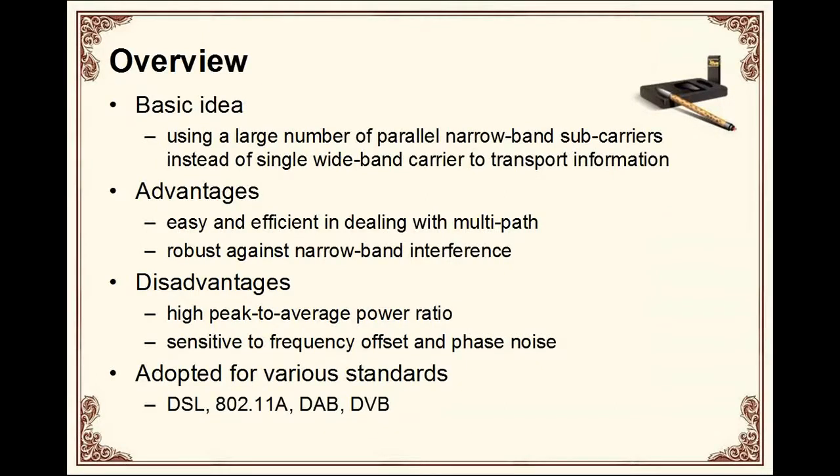But it has some disadvantages, such as a high peak-to-average power ratio, and it is sensitive to frequency offset and phase noise. I will talk about this in detail later. It is adopted for various standards such as DSL, 802.11a, DAB, DVB, etc.